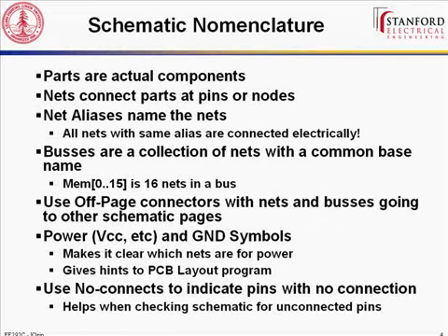It's also good when you just visually are going back over your schematic and you want to make sure, did I connect everything? Did I forget anything? If you have a no connect there, it means, yes, I've thought about it and this really isn't supposed to be connected. So please do use them. And that's going to be a requirement for designs you turn in this class. Don't just have floating pins. So any questions on basic schematic nomenclature here?